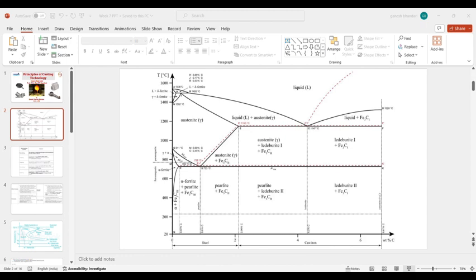Okay, so to provide that ductility, we have to go with the process annealing process. What we will do is heat treat that steel below the lower critical temperature, because we don't want to convert the phase into austenite. We just want relieving of stresses from that steel, so that the high hardness value of that steel becomes lower.